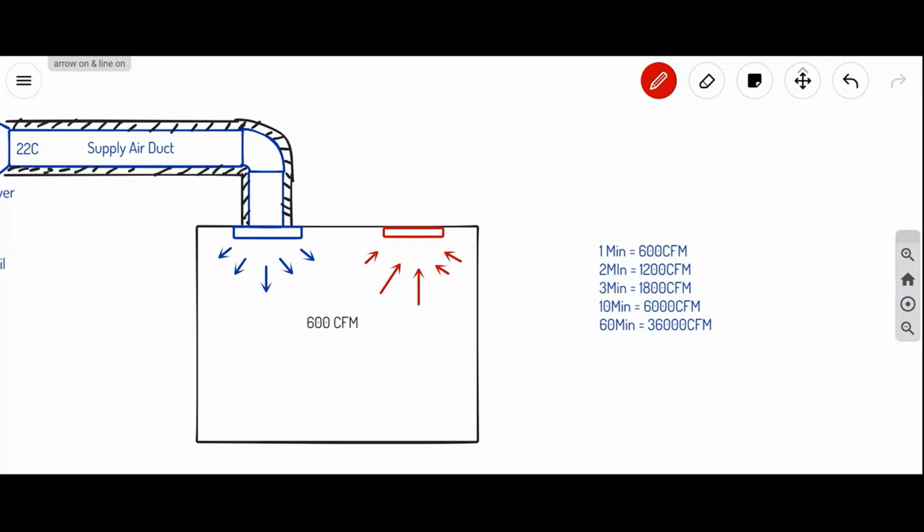That's why we design properly. For example, if we need 5 TR chillers and we put 10 TR, this is the energy loss and the cost is high. That is why we do the calculation, to take exactly what is needed.